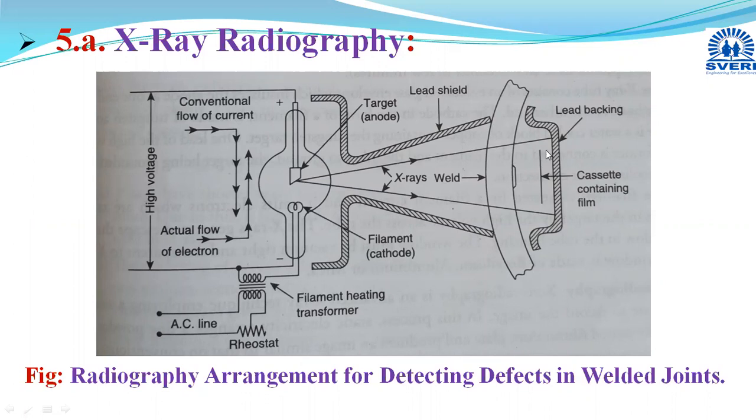The dry plate is an aluminum-coated plate with some powder inside, and the image is recorded on that plate within 45 to 60 seconds. Within that time, the output of the radiography is obtained. This is xeroradiography.